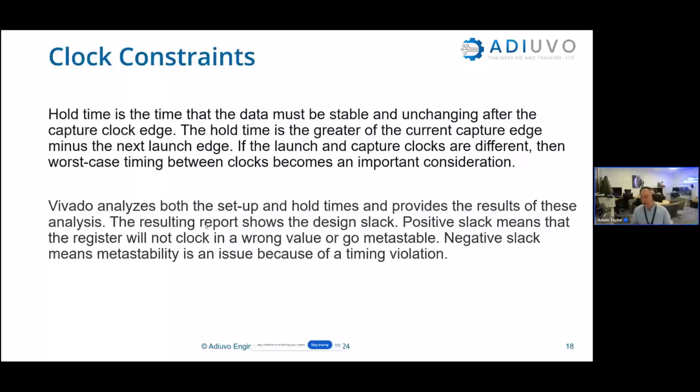Now, Vivado is going to do all this analysis for us when we ask it to do a timing report. It's going to run through and analyze the setup and hold times. The exception to that, obviously, is that we need to tell it if we're doing I/O type stuff. And it's going to give us a result that gives us what's called the slack in the design.